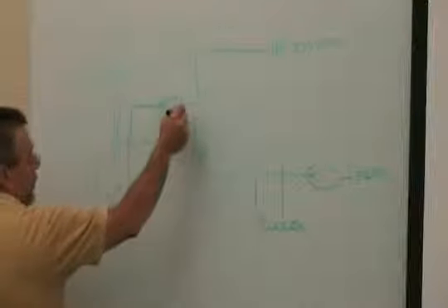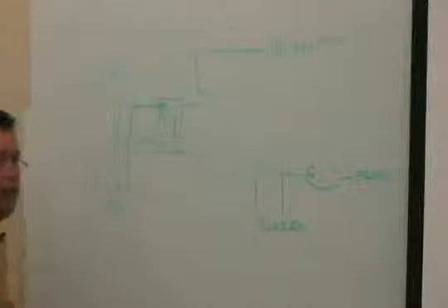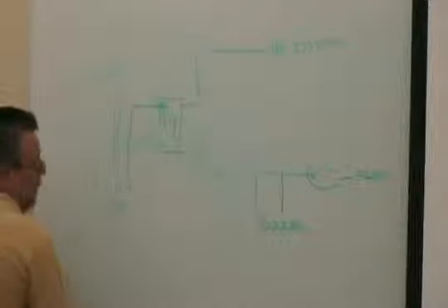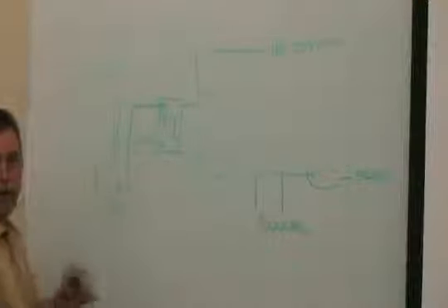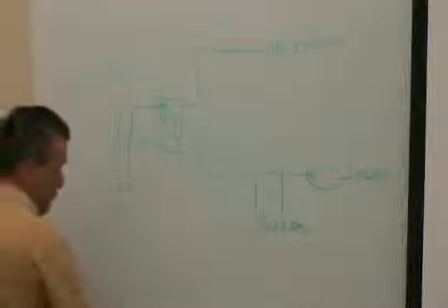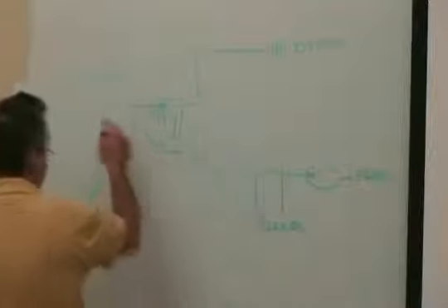If I've got 85 up here, I could probably get that even down maybe to 90 with a flat plate heat exchanger. And anytime I can get this water temperature lower, I reduce my compressor lift. So on the boiler, there's the cooling tower.